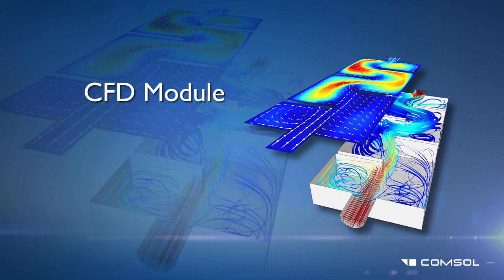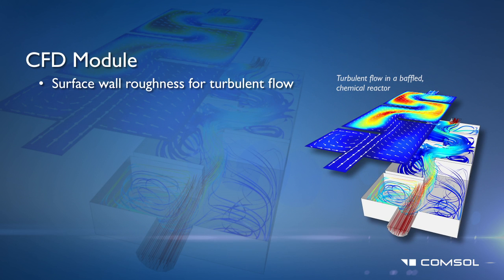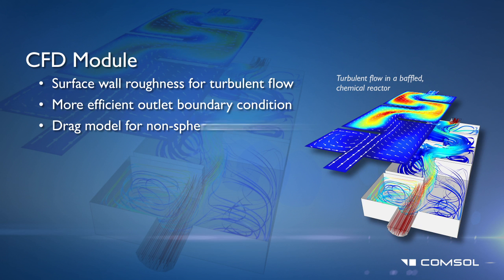Further improvements have also been made to the fluid flow capabilities within COMSOL. This includes a feature to define wall roughness for turbulent flow, a new boundary outlet condition for improved mass conservation with faster and more robust convergence, and the introduction of a drag model for non-spherical particles.